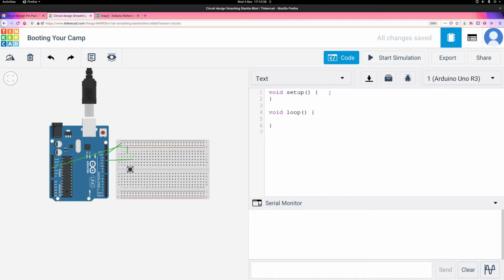Yes, and Jacob has also spotted the other one. Look at you, an Arduino expert. Yes, so you can also do what's called a pull-up. Well, okay, so we'll see the issue, then we'll see the solution, which is a pull-up resistor, and we can also see that in software. Arduino lets you turn that on in software instead of needing to add it to your board. So, yes, very on point.